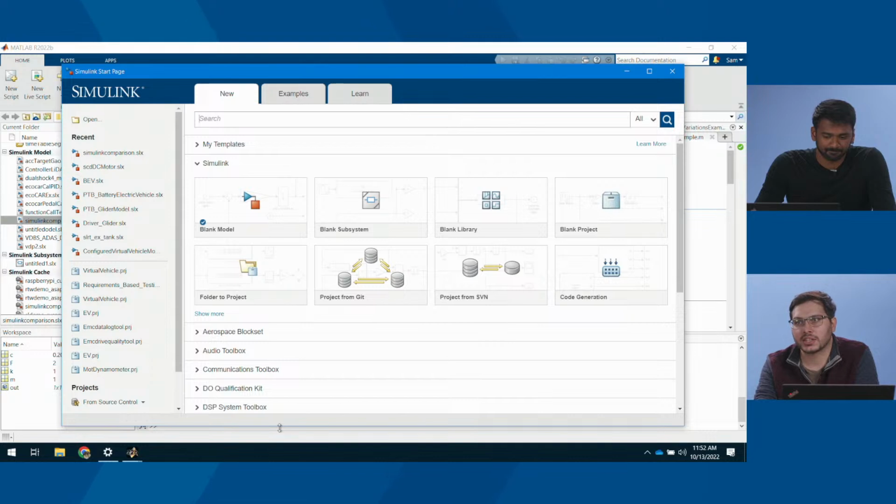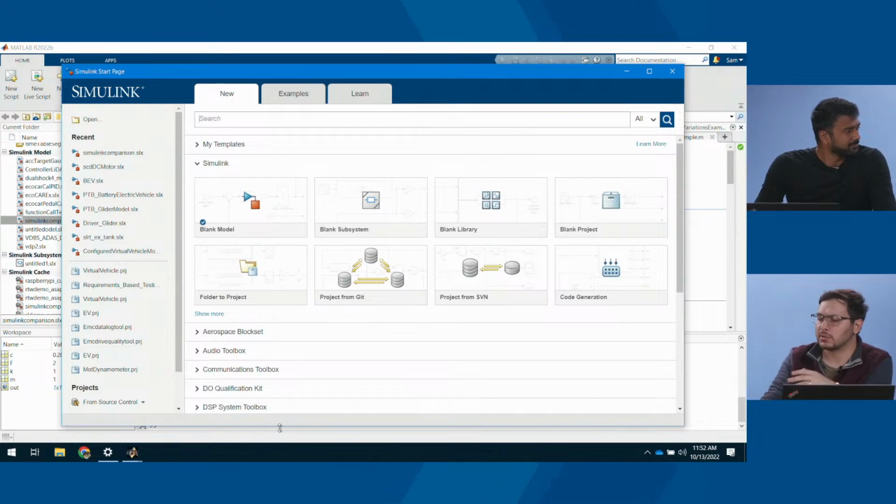Like what I did right then, I had to write up all the equations for all my systems. Simscape is dedicated to physical modeling where maybe I know the equations that represent an individual component, and I'm going to piece a bunch of these components together, and they have directionality. Like what happens in my electrical circuit impacts what's happening in my battery. And rather than trying to do all these loop backs, Simscape is a really good tool for modeling that kind of physical system.